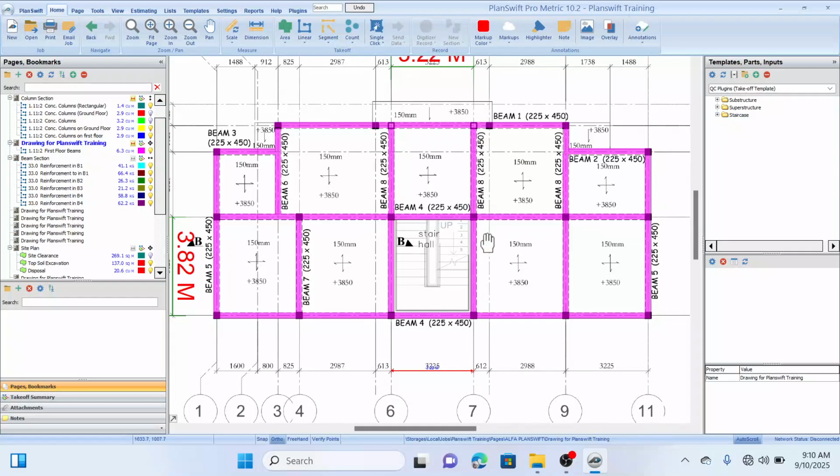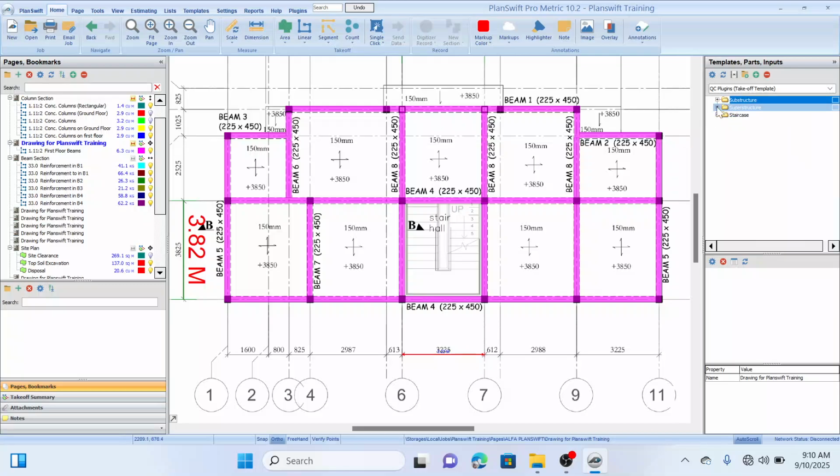As we all know, our concrete in slab here, suspended slab, is part of superstructure. So we open our superstructure folder, and what we have here is our concrete suspended slab. I'm going to click on this to have access to the content of this folder. And what we have here is the plugin. As you can see, we have formwork, but the reinforcement plugin is not part of this. So I'm going to measure the reinforcement separately, the way we did for our beam in the previous video. The only thing we're able to measure with this plugin is the concrete work and the formwork.